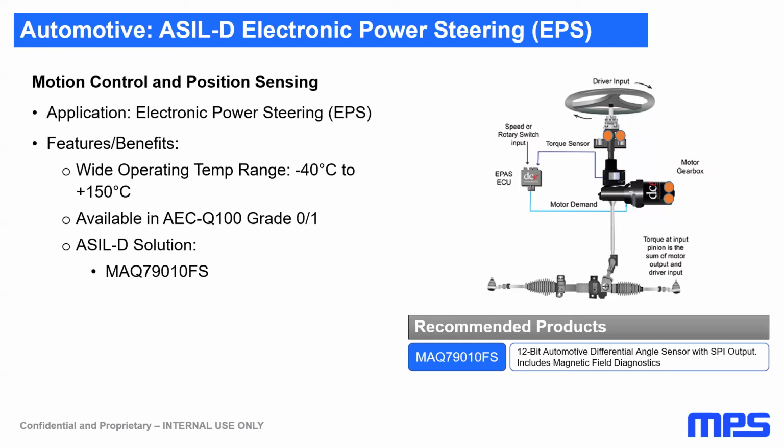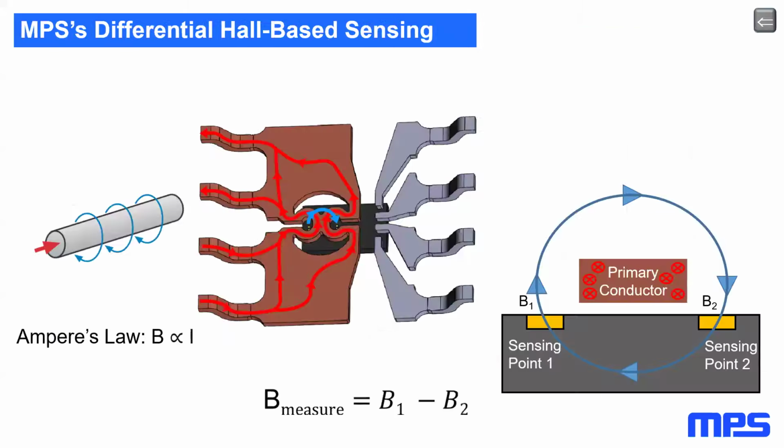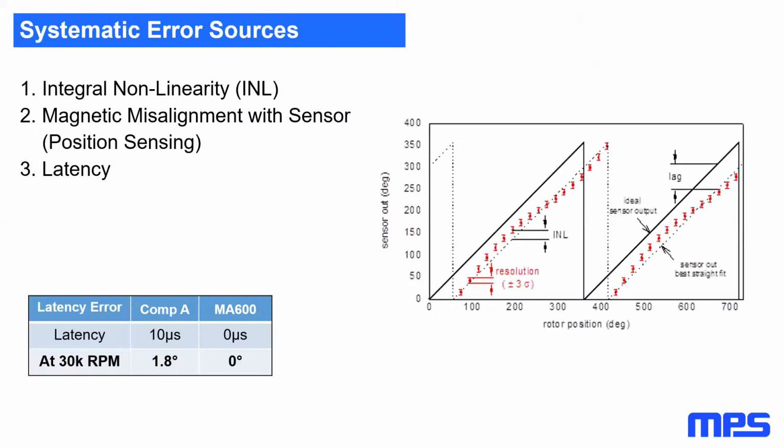You have mentioned the immediate latency correction of the position sensor. Is the working principle kind of a continuous loop monitoring the speed from the position and correcting the output in real time? Yes, it is. For our MA600, the part that I talked about that has the zero latency, I talked about the resolution filter, the noise filter in the sensor. That filter is built with a position state variable and a velocity state variable.